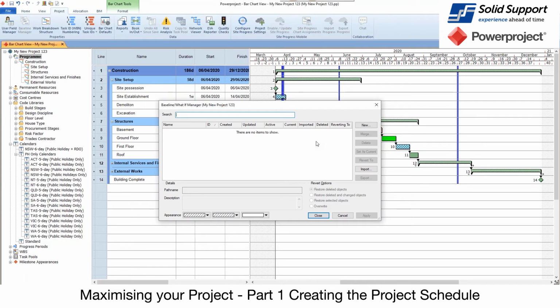Now, unlike other systems, Powerproject will remember everything about this project. It's not going to just remember the start and finish date. It's going to remember start and finish date, links. It's going to remember every setting about every activity. What calendar it was using, what codes were assigned and so forth in there. It's a complete copy. And also there is no limitation to how many of these baselines you have.